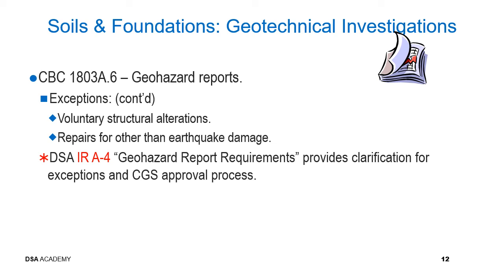Geohazard report usually identify if there is a mitigation required. As inspector, you need to pay attention to that, because if mitigation is required, many times CGS has to approve that mitigation if it's deferred before any foundation work can start.